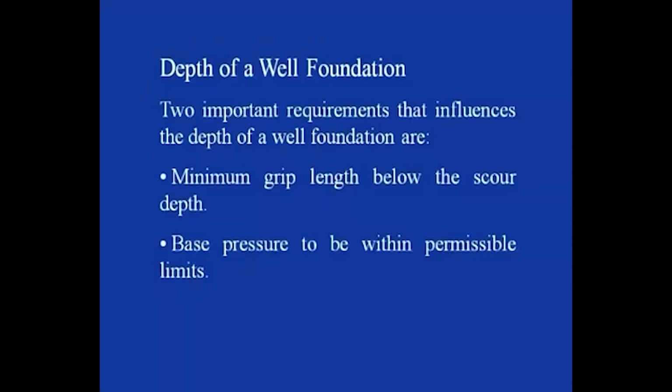There are two important requirements that influence the depth of the well foundation. The first one is the minimum grip length below the scour depth, and the second one is the base pressure, which is to be within the permissible limit.